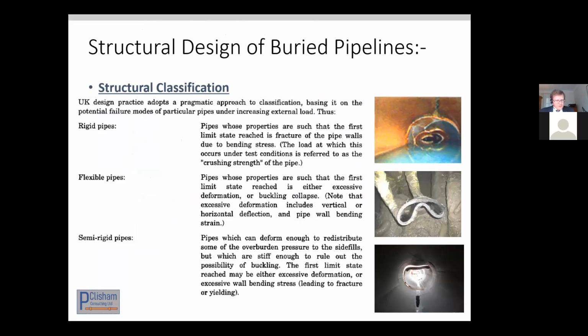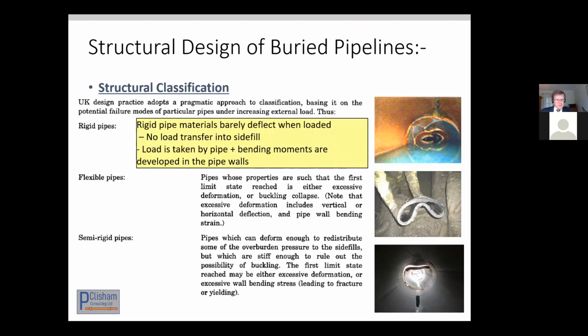So from a structural point of view, there are three fundamental classifications. We have rigid pipes. Now these are the pipes that don't bend and flex, something like a clay or a concrete. Ultimately, they carry the load themselves. They transfer it down into the ground beneath them. And ultimately they'll crack and break rather than bend and flex.